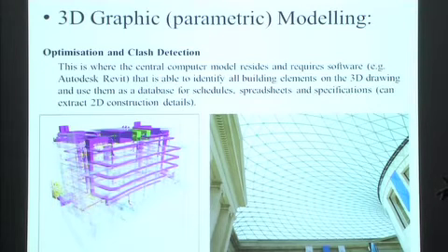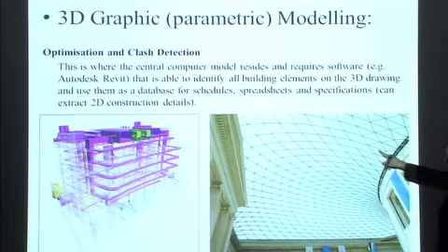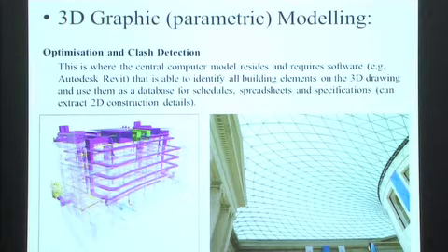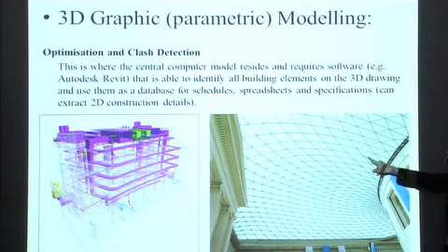And it's the first time that I've ever seen parametric modeling as a computer program, because Arup, I think, devised a program, and I saw it working in real time, where you've got a rectangle, you've got a circle in the middle, you've got this system, which is a combination of tangential and other angles to make the triangles, and you pulled that circle very slightly off center, and everything started to reconfigure itself around it. Now the idea of the optimization was to minimize the variations of triangles.